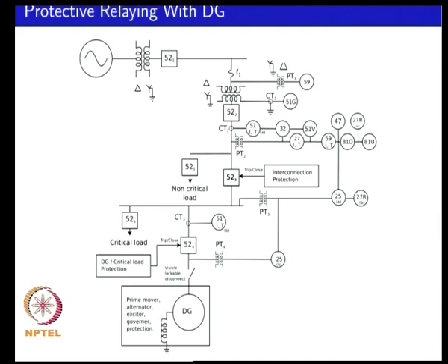So, another thing to keep in mind is that all of the relays that are implemented are standard relays. I mean, you do not have something which is not already available as a standard. The only thing which could be considered as not already there is the issue of how to detect unintentional islanding, especially when you have a wide range of situations.